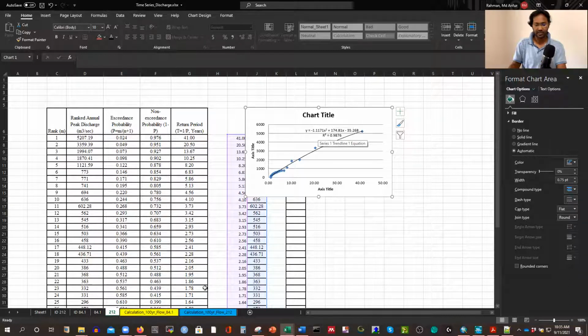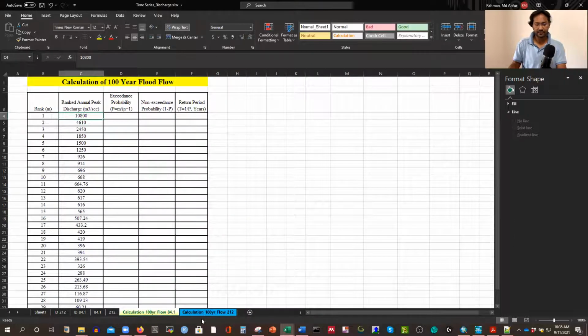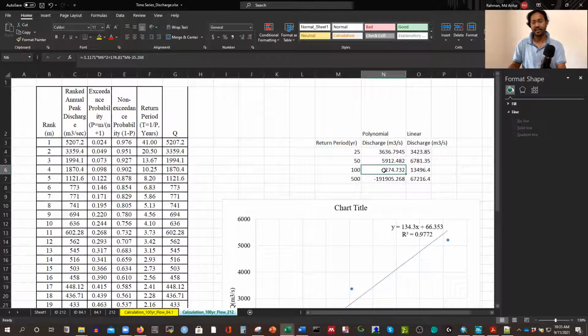That one, exactly the same one I used previously. So if you use the same one, that is okay. So we can select this value. Okay, I'm selecting this value. Keep in mind that we have the flow rate, this one, and for water level, we'll use this value 6274, or you can round it to 6300. Okay, 6300 cubic meters per second. That is the 100-year return period, and we can use that as 6000, right? And we can use that as 3600. So we are going to use these values.